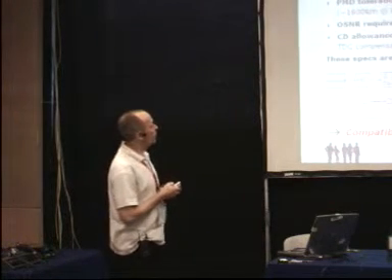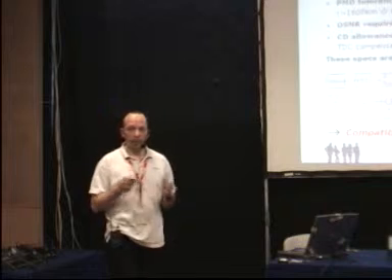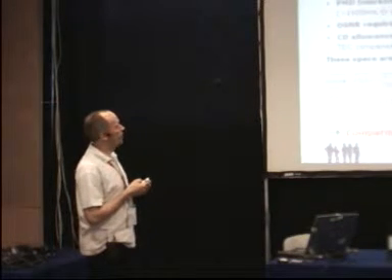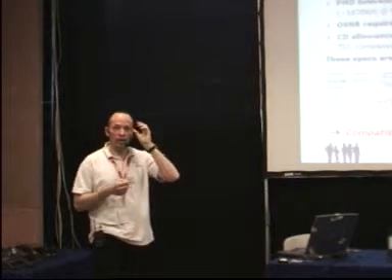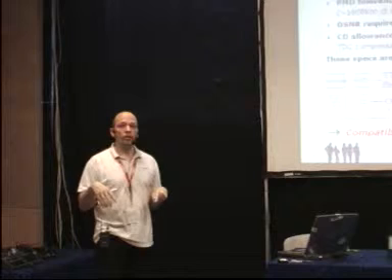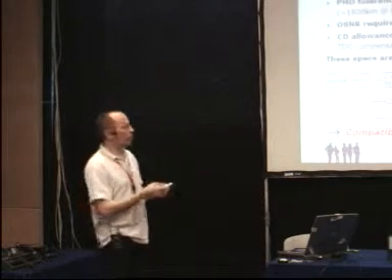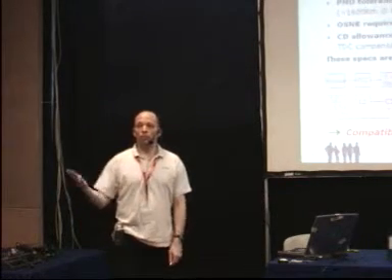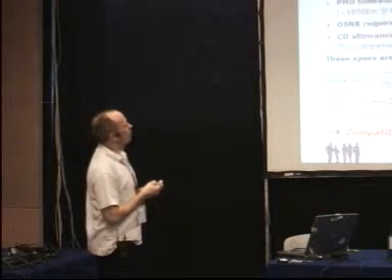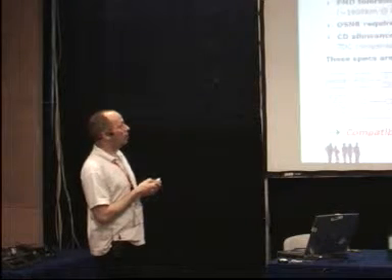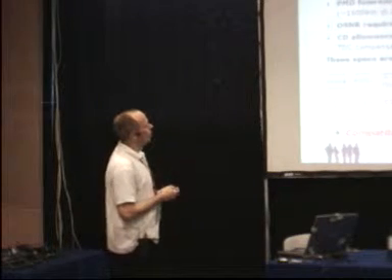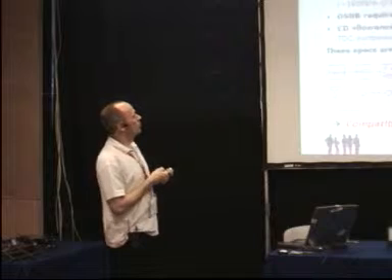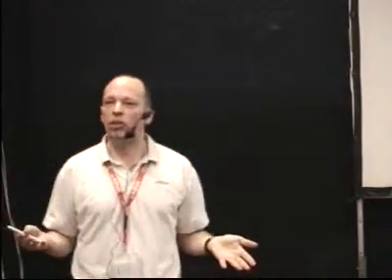The very good thing is it works really pretty good, carrier suppressed return to zero. In effect, it has 9 picoseconds PMD tolerance, whatever this exactly means. Our own metro 10 gig gear has 10 picoseconds, not much more. So this system supports almost the same PMD as our 10 gig gear. Same with the OSNR. Our 10 gig transponders do require approximately 17 dB as well in the best case. And also with regard to chromatic dispersion, because this allowance window of 400 picoseconds per nanometer is approximately the same that you can find in typical metro systems.